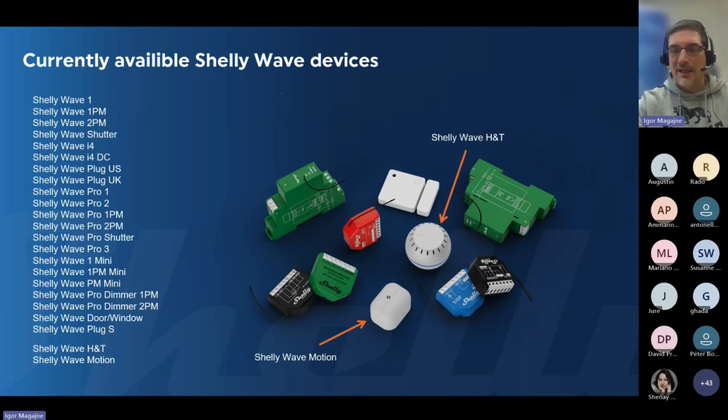If you try to include a device, it will get a node ID from the gateway, marking the node ID and home ID, so the device will know that it is included. Now, what happens during the inclusion is there is an interview, and for some reason it does not complete, and the device basically remains with the node ID but not included, so that device is, let's say, not included in the gateway. What you need to do is just reset the device and try again.